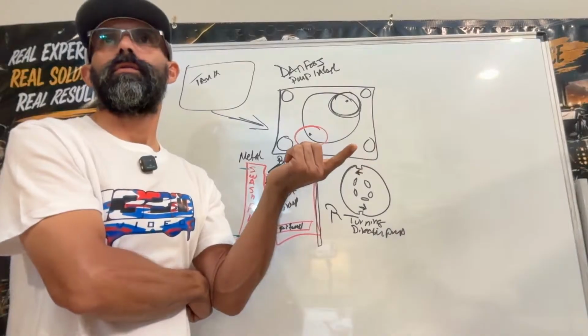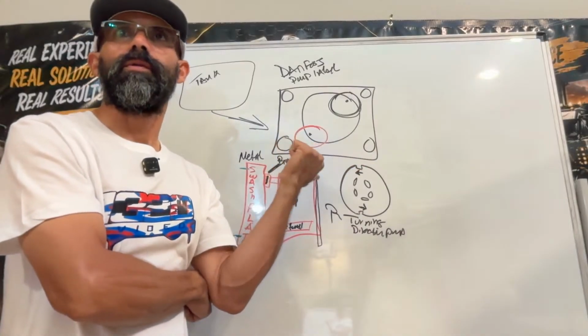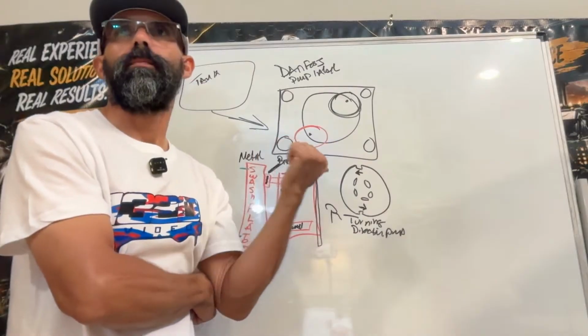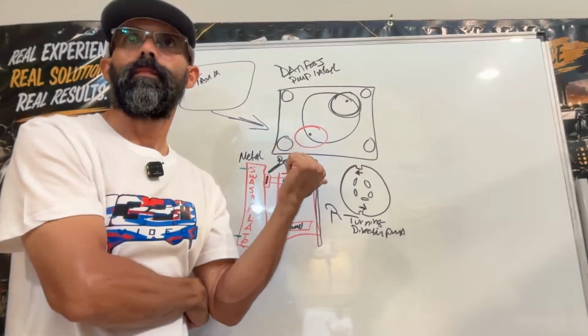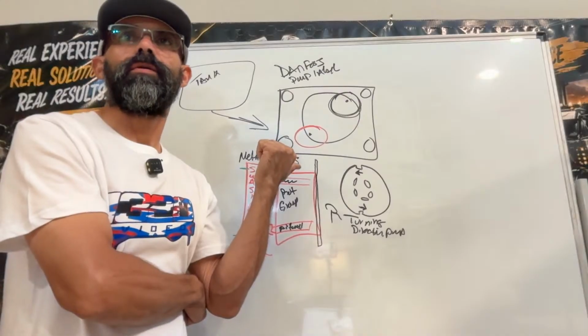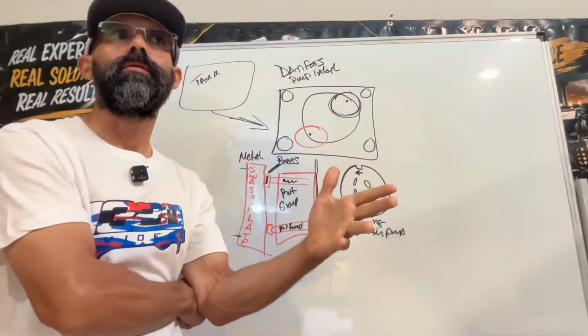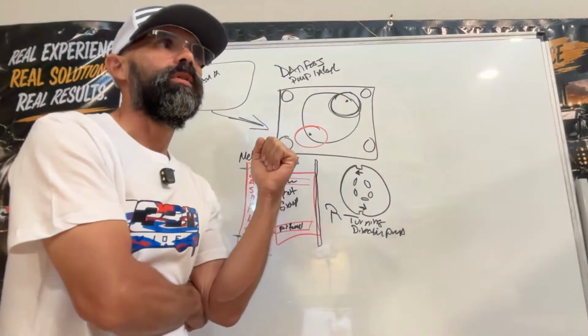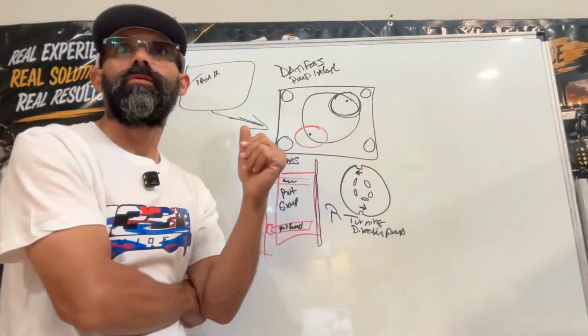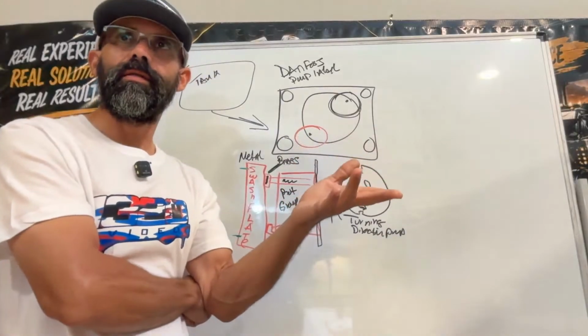Use good filters, because using good filters also helps keep the pump running, and keep up with the maintenance, with the manufacturer's suggestions. If he tells you within 250 hours this needs to be serviced, within 500, 1,000, 2,000 hours, 3,000, 5,000 hours, whatever, just follow the maintenance.